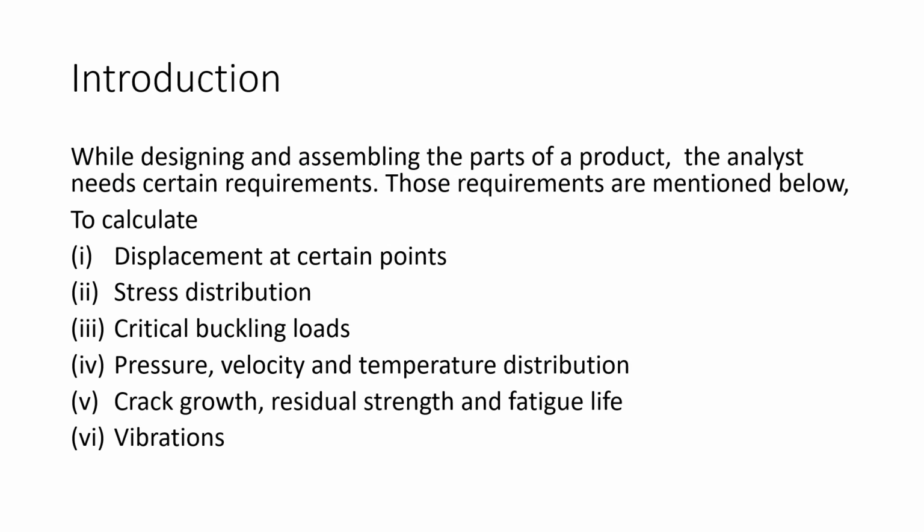As an introduction, let us see what the requirements are for an analyst when he designs a product. Displacement at certain points, stress distribution, critical buckling loads, pressure, velocity and temperature distribution, crack growth, residual strength and fatigue, vibrations, etc. These are the variables to be checked when a design is completed, after design is completed and before the product goes for mass production.